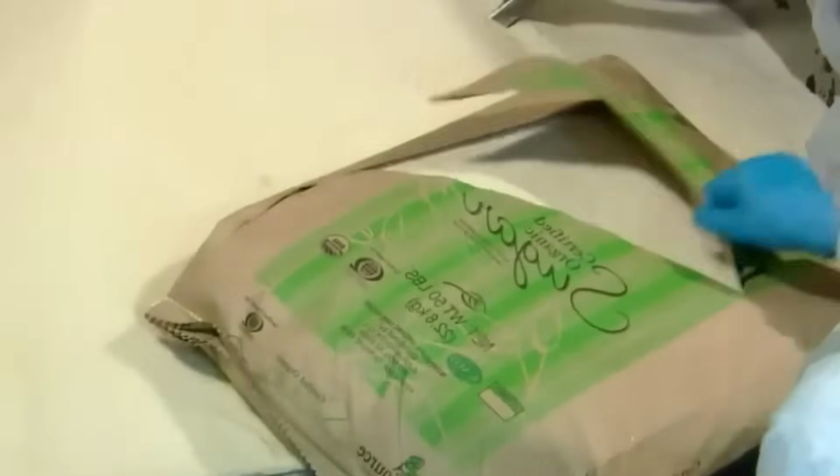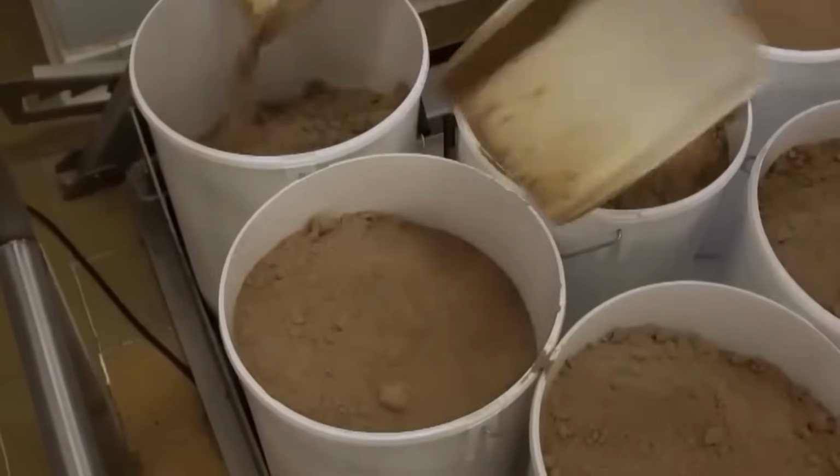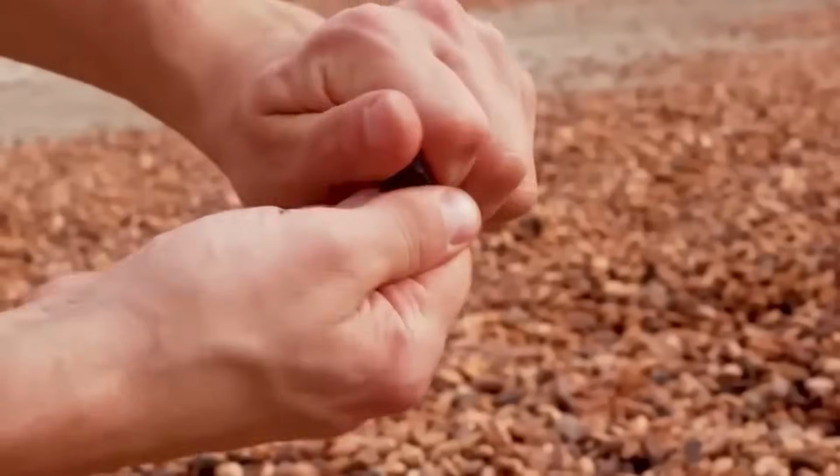Dough temperature is maintained between 22 and 26 degrees Celsius. Moisture content is monitored via inline near-infrared sensors and must fall within 10.0 to 11.5% before release to the forming line. Dough is transferred via a covered screw conveyor to a pre-sheeting station.